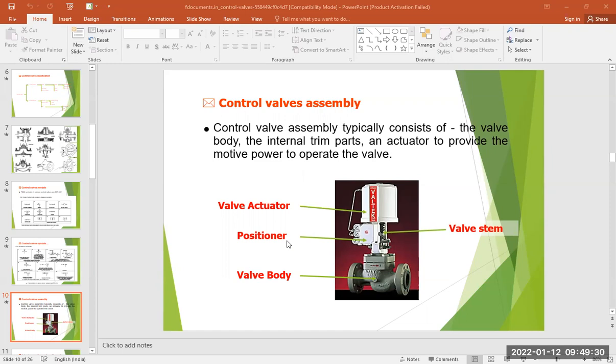Okay, you have to easily understand that when you use the pneumatic type of positioner system, in this case we control the air pressure for the input section, and the unit is 3 to 15 psig. Okay, so this is the input pressure supplied from the actuator to the positioner system.